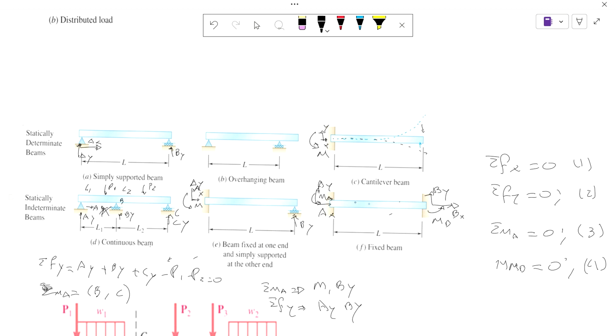We are assuming it's not going to break under those forces. So at that point, we only care about the external and some internal forces. But if you wanted to find the internal forces, then you have to use some microscopic methods where you go point by point, such as finite elements, finite volumes or finite differences, which are numerical methods. Or you can try to obtain a partial differential equation and find the exact solution for it. So for this type of example, you need to know the boundary conditions. You need the forces to be able to solve anything internally.